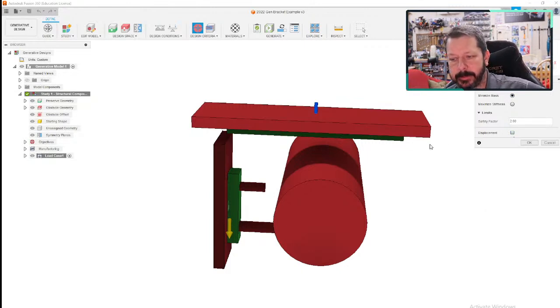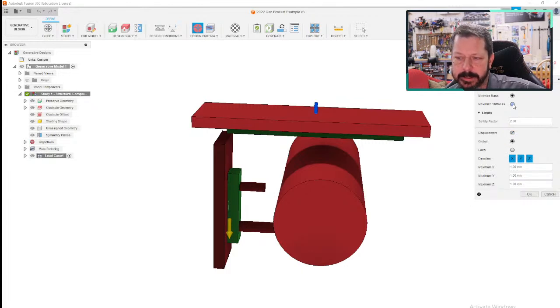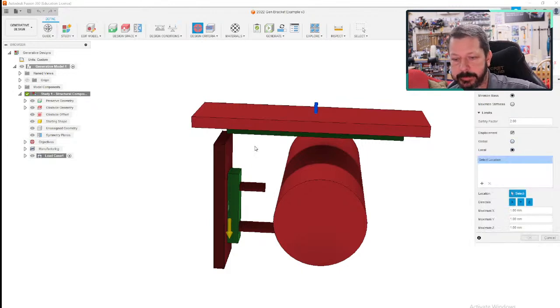I did not define one on this one. I think I left it blank. That's related to the stiffness, but in a different way. So you could be more specific, instead of just some stiffness idea, and say it cannot deflect more than this distance, either globally, anywhere, or at a specific location. So you'd have to select the location that can't deform.